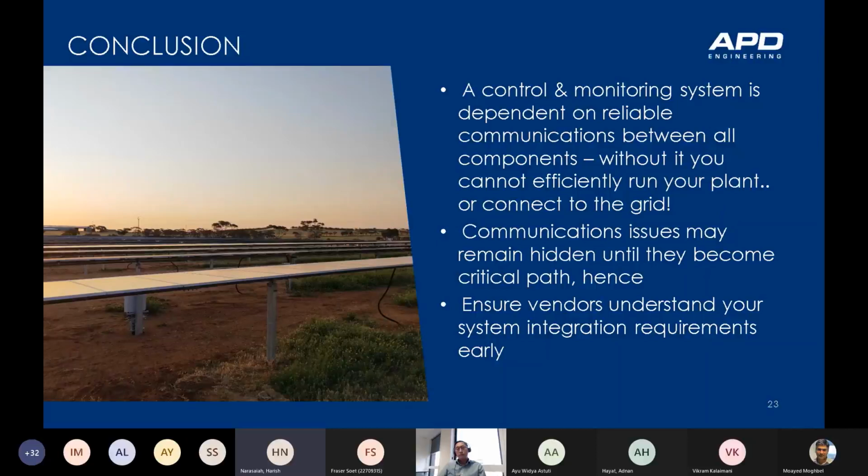Oh, I don't know. Good question. In projects that we've been involved with, it sounds to me like you have a lot of network devices. It's almost like a comms FAT, in terms of establishing rings, network segments, LANs and all sorts of stuff. That kind of stuff you should have done in a lab and ticked off before you take it to site.